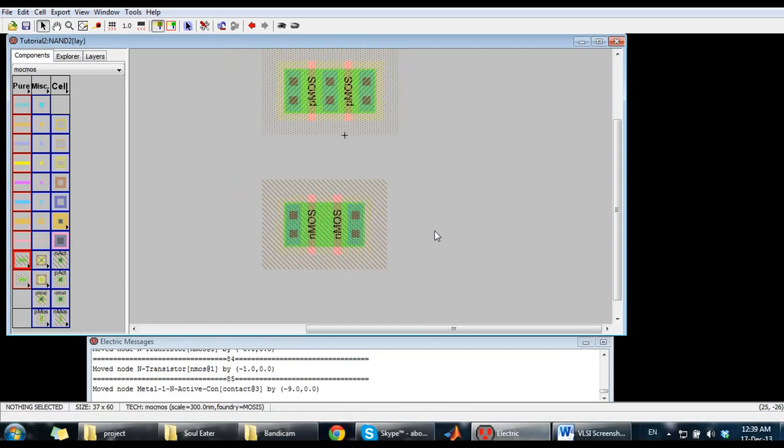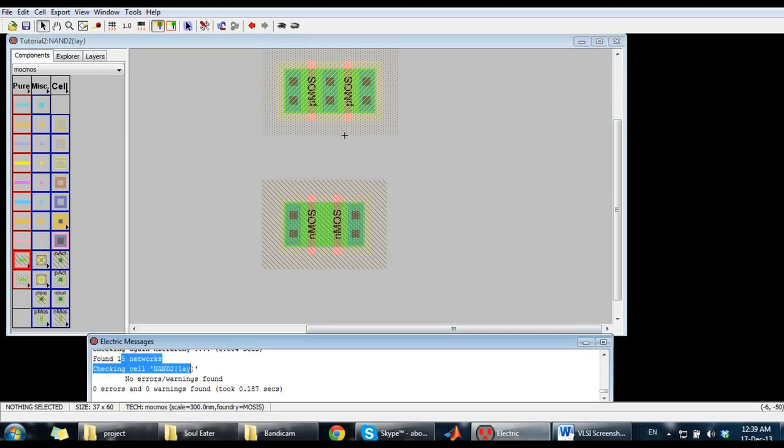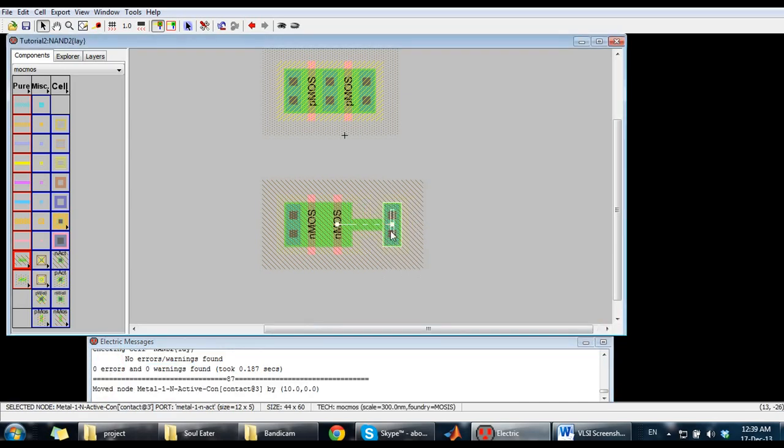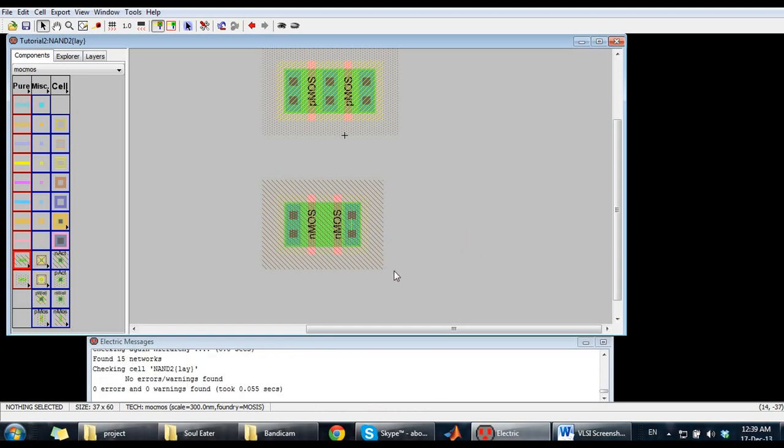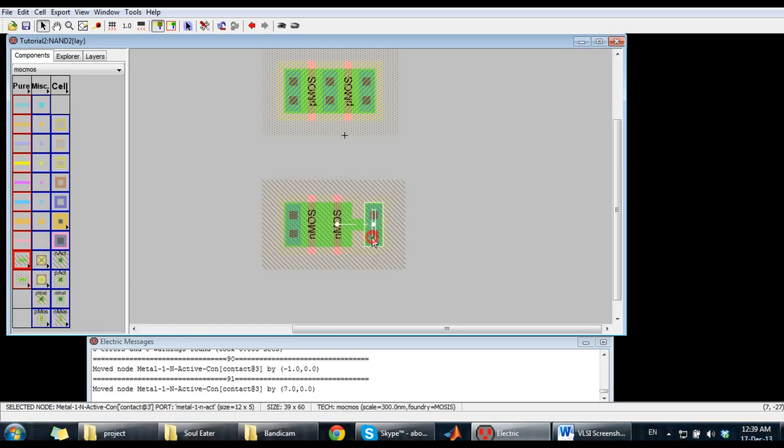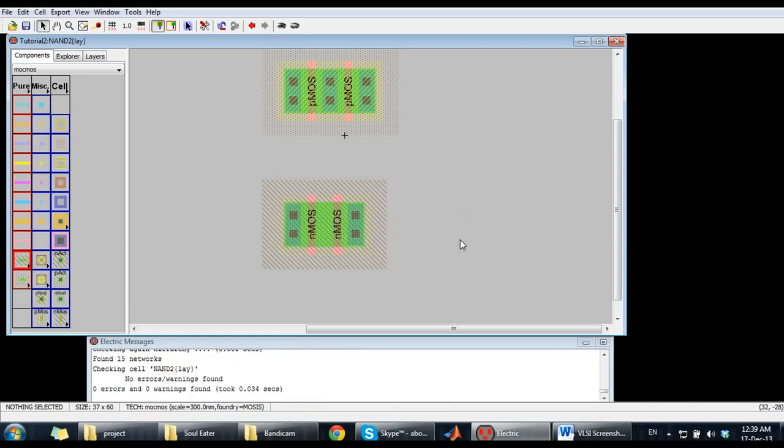Okay, after doing so, every once in a while just press F5. As you can see, it will give you a quick review. It's somewhat like compiling. It'll show you any errors or warnings. Let's say I make this too close, and it'll give me an error, and I know I'll find an error, and then I'll press F5. Okay, why? So we just leave it for now. Okay.